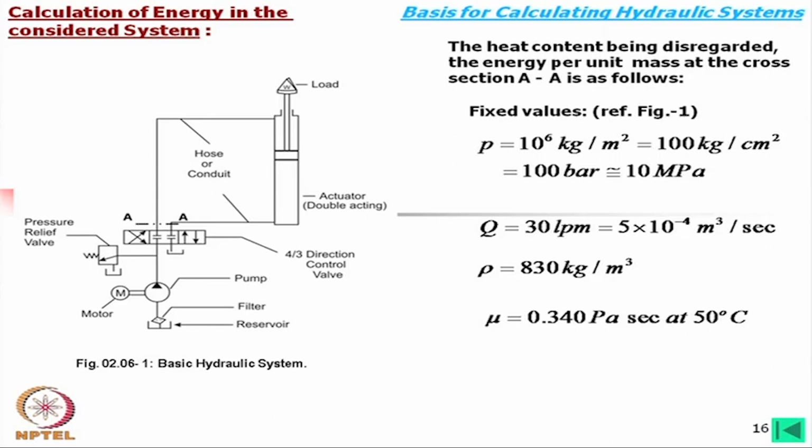And in cold country, for cold start, oil temperature may be less, but when it starts working, usually you will find that oil temperature will increase because of the friction and other things, and maybe 30-40 degrees centigrade the oil temperature inside it, even if the ambient temperature may be 0 degree.